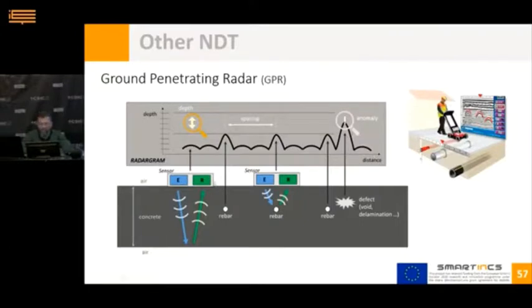By analyzing the radargram, the reinforcement position can be identified, and the covered concrete can be evaluated to determine its thickness and to detect possible hidden heterogeneities or defects. Ground penetrating radar equipment is usually coupled to a rolling system to facilitate the inspection of large structures.